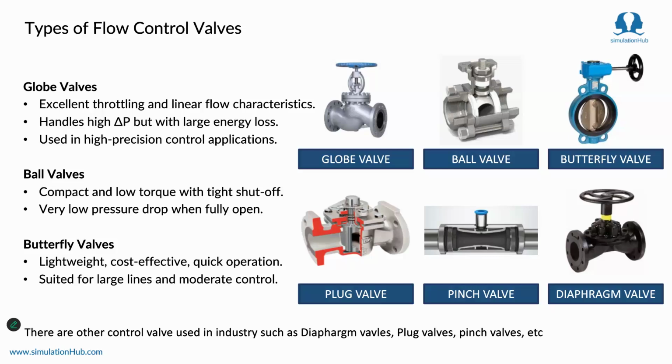And butterfly valves are also used in control applications. They are suited to large valves, basically controlling flow through large pipes. You might have seen them in water management industries and oil and gas, where butterfly valves are very readily used.